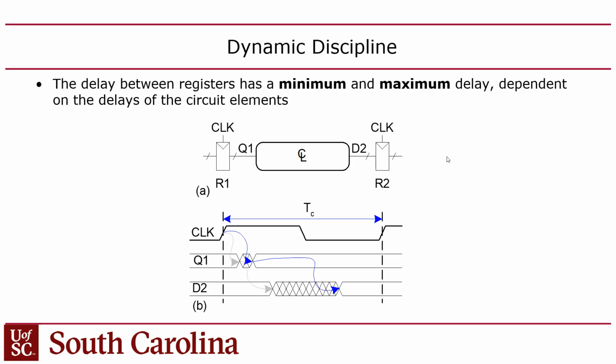You subtract to figure out if the registers are equal. Then the value from the ALU goes back into the control unit and is compared to what branch instruction you're doing, and it determines from the output of the ALU what the program counter source, the PC source, and the stall signal should be, right?